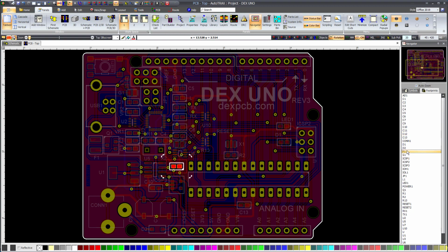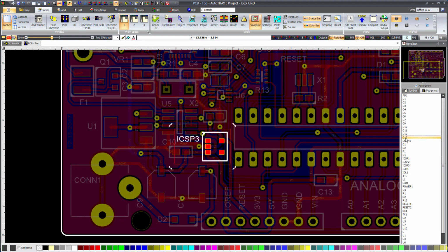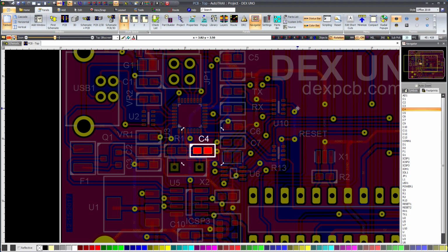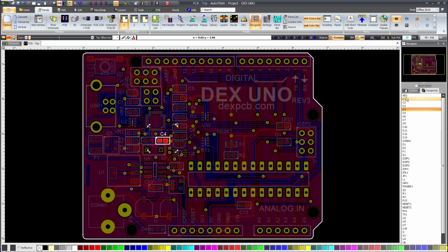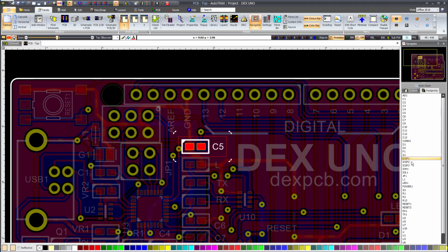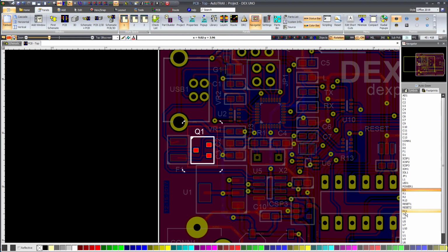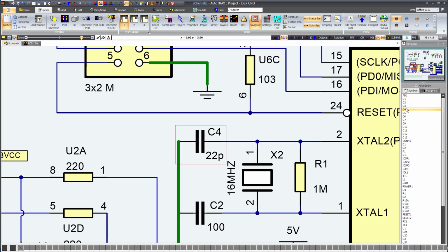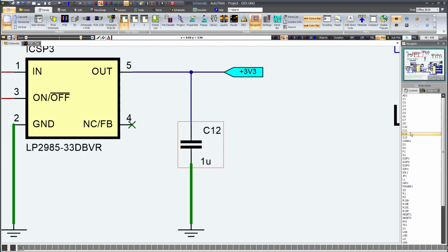If you disable the auto zoom feature and then press the home key to fit the entire layout in the viewport, selecting a footprint will highlight it and dim the rest of the PCB for better visibility. Re-enabling auto zoom and selecting different footprints will cause the viewport to zoom in on each one in turn. Returning to the Symbols tab and selecting a symbol will automatically bring up the schematic in the viewport with the chosen symbol highlighted.